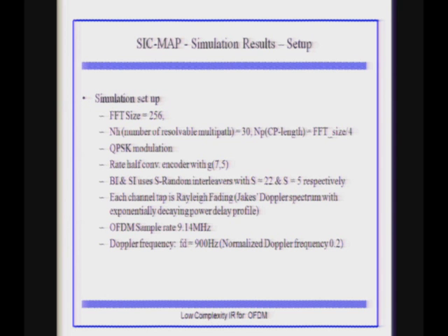There are schemes you can devise. From her research group, they have come out with some schemes whereby they do not have delay, and that is by not introducing the coding in the path. Instead, whatever is coming out from the equalizer, they take the LLR and get the mean value and variance. But when you do that, you don't take advantage of the coding gains and performance suffers.